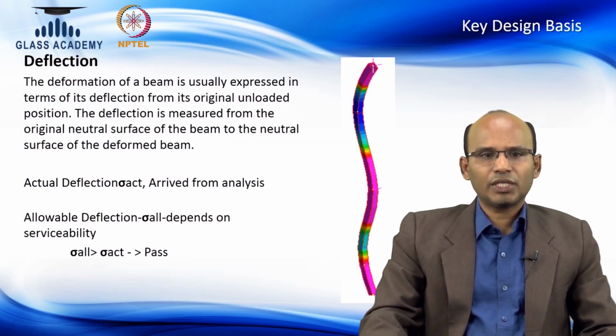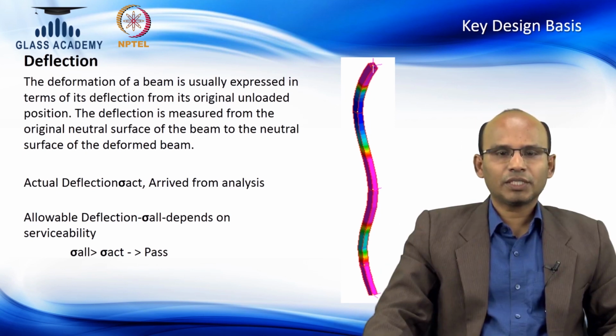We have been checking for strength so far. Here we are checking for deflection. A deflection check is critical to make sure the member is deflecting as the engineer is assuming, and this is going to be deflecting for wind loads, or sometimes for live load. So the members and glass elements need to be checked for these different criteria. It is primarily driven by the wind loads, which could be negative wind load or positive wind load.